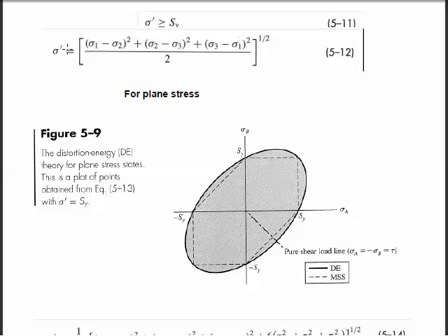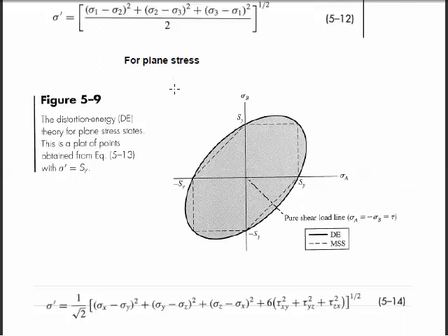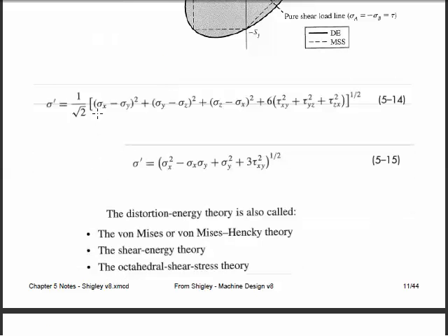We won't have that terribly often in this class. If instead we have our full triaxial state of stress with sigma x, sigma y, sigma z, and all 3 taus, that would be the most complicated cube that we could have, then we can calculate the von Mises stress from this equation, plugging in all 6 numbers.